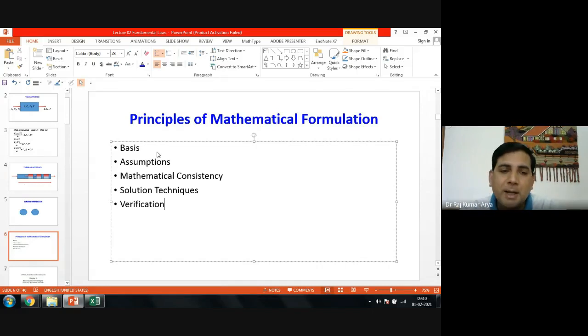At the same time, if you say no, I will validate with the shear stress variation, you know how the shear stress would be calculated inside the pipe. It's the most complicated exercise, and the chances of error are very high. If you validate your model with that, you will always end up with a wrong validation. I'm not saying the technique would fail, but it is not a parameter which can be measured directly with more confidence. So the easiest possible one is the flow rate.